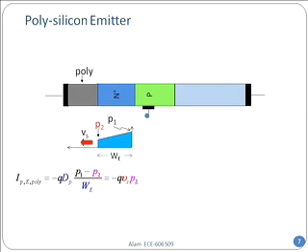Now, that current must be equal to whatever rate at which polysilicon can take it out. And polysilicon takes it out as minus Q V sub S, which is the surface recombination velocity. Here, it's not really recombining at the surface. It is very different from the previous case that we saw, right? Surface Shockley-Read-Hall. Do you remember in that case we had a surface recombination velocity? It is not that. It just limits the velocity at which electrons can escape to the polysilicon, multiplied by P2, because that's the concentration I have.